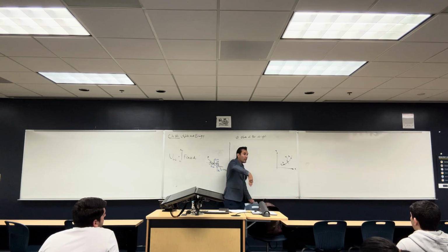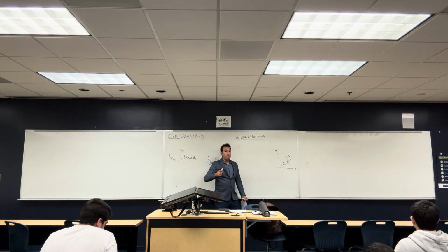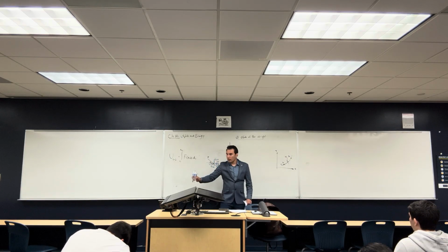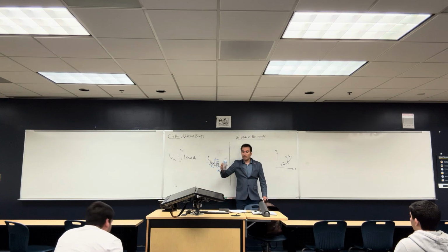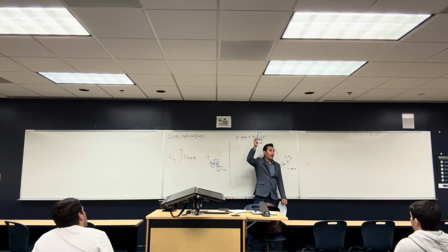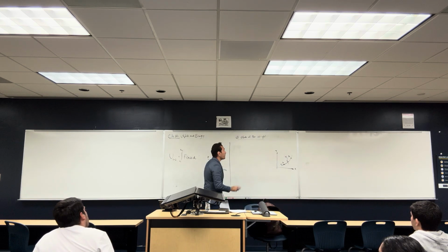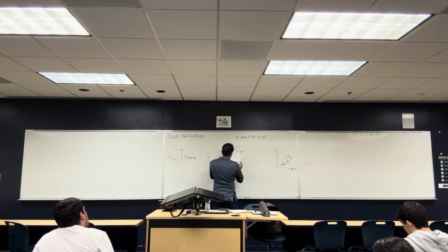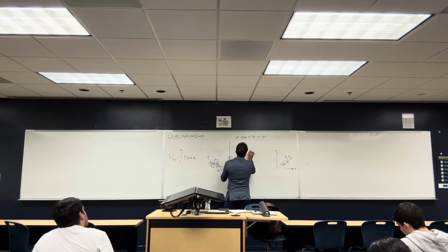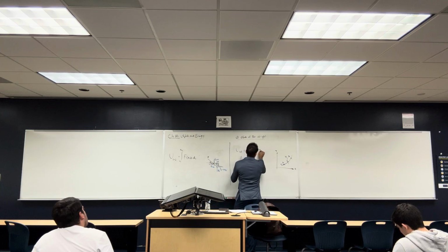But the weight is always down, so it doesn't matter if you bring this body from here to here that way, or that way, to the same level, it's still the same amount of work that you have to do. The work done by the weight, let's say U of the weight, is going to be equal to negative W, it's always negative, multiplied by Y2 minus Y1.